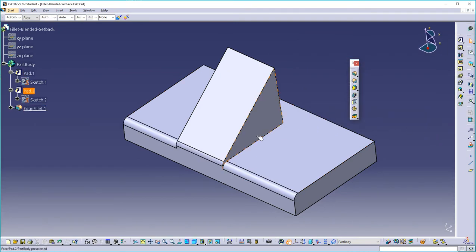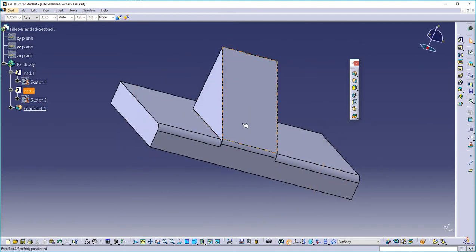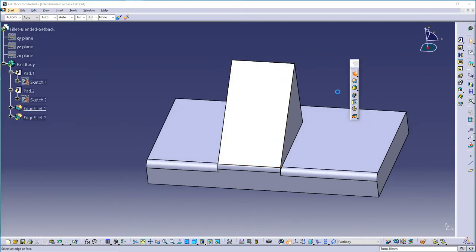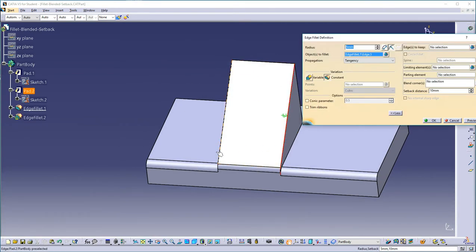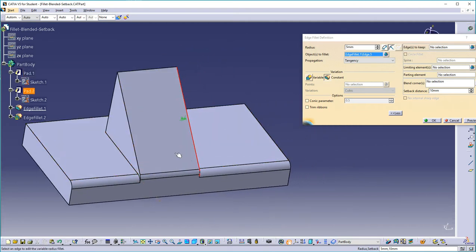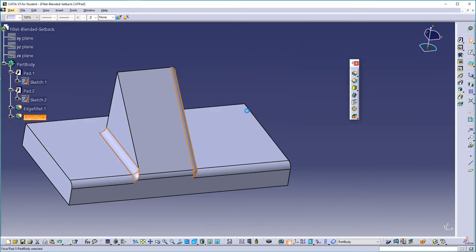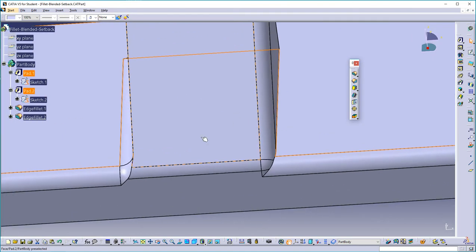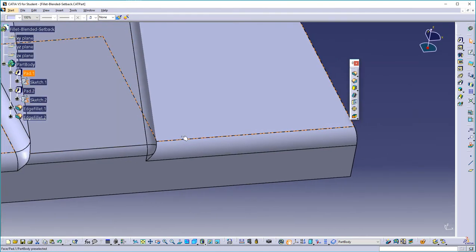Okay. Now let's fillet in here. And let's pick the top one first and then the bottom. And on the other side, we'll pick just the opposite way. Okay, so let's pick the fillet option. Let's pick the top one on this side, but on this side, we'll pick the bottom one. Oops, just that bottom edge. There you go, and say OK. And you notice that there are two dramatically different looking fillets so far.